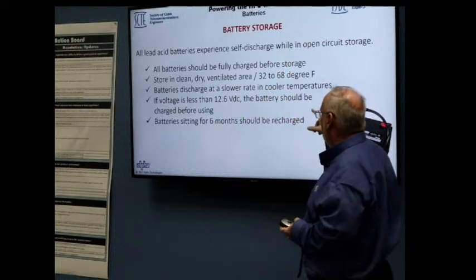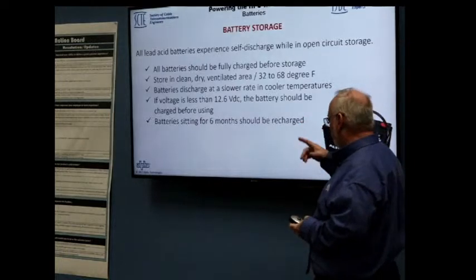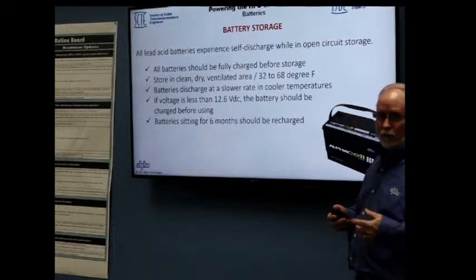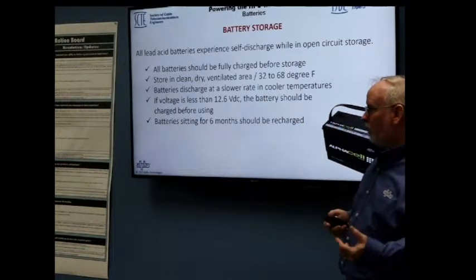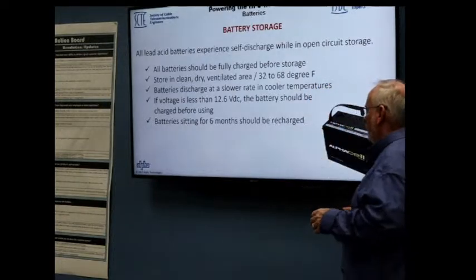If the voltage is less than 12.6 standing, the battery needs to be charged. Batteries sitting for 6 months should also be recharged. There are some newer technologies where manufacturers say they provide longer periods. If you recharge at 6 months, you'll never have a problem.